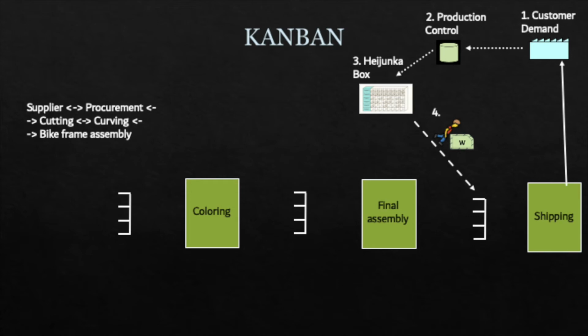In step 4, you can see how the milk runner, as the first thing in the morning, goes to the Heijunka box and picks up all Kanban cards that are placed in the column for the first 2 hours. 2 hours because this is our predefined time interval as mentioned before. With those Kanban cards, he walks to the inventory just before the shipping process.